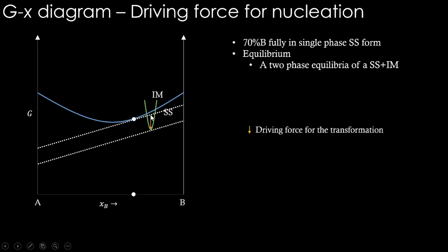So I am putting it here to show that it touches here. It need not touch the bottom. Okay, it can touch anywhere. The curvature here is quite sharp. That is why you are seeing it as if it is touching at the bottom. But if this is a shallow curve, it need not touch at the bottom. It can touch anywhere else. So the distance between these two is the driving force for nucleation.